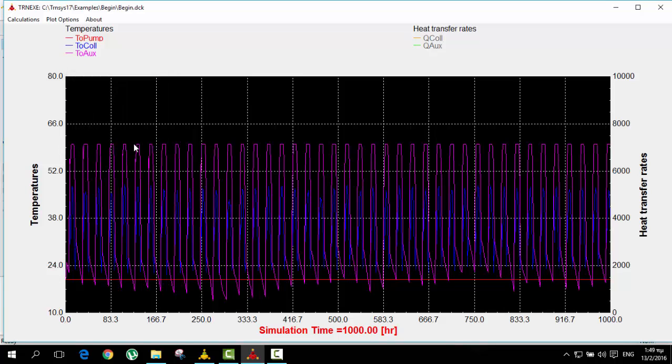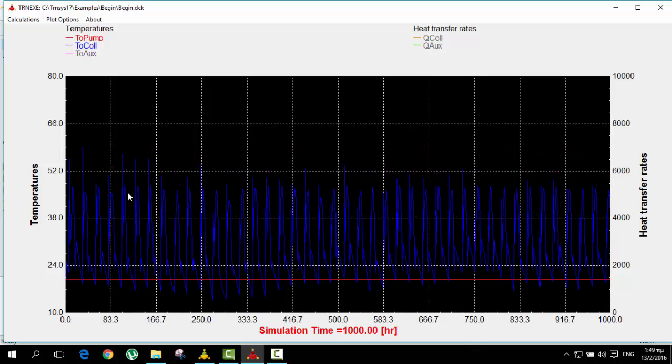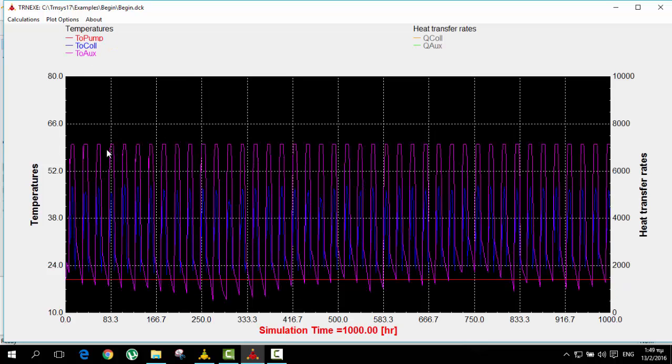That's why we need the auxiliary heating sometimes, because we have set the warm water for us to 60, so we want 60. The blue is not enough, it's not reaching 60 unless sometimes. So we have to operate the auxiliary heating so it can take the water to 60 degrees.